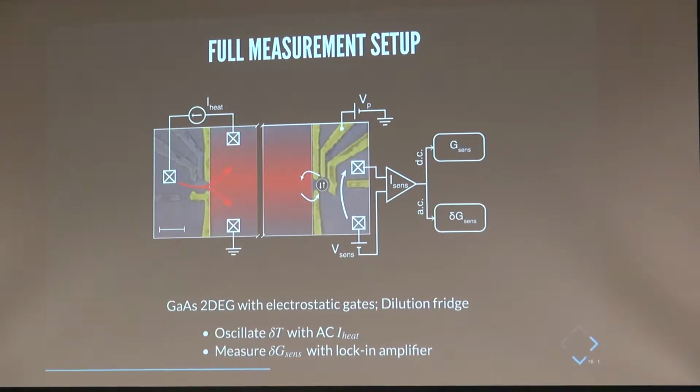So we find that it doesn't vary up to a few hundred hertz where our wiring starts to stop being reliable. So I think we typically work at about maybe 50 hertz for I heat, which the heating happens at double the frequency, so it's about 100 hertz. But we've played with that frequency, and it's really not affected by anything until our wiring starts to crap out.